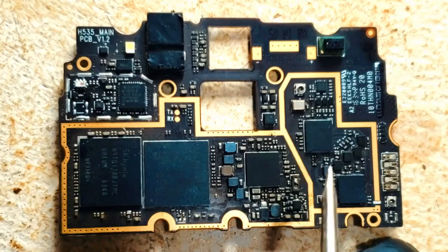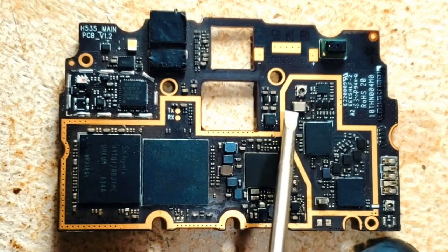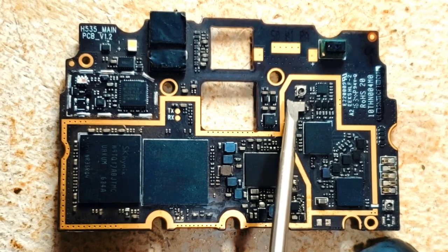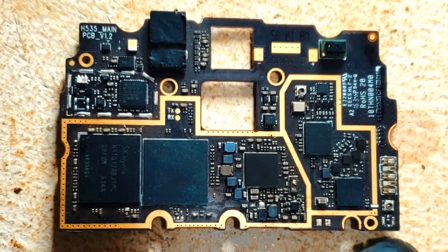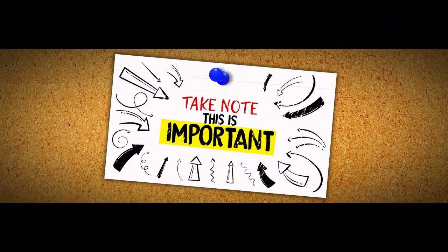How to identify the 26 MHz crystal oscillator? Well, this component is found around the PFO in the network section. You will observe that this component is mostly shiny and has a metallic makeup. Here I must also remind you that any PCB of a mobile phone is divided into 3 sections, namely, 1. Network section, 2. Power section, and 3. Processing section.